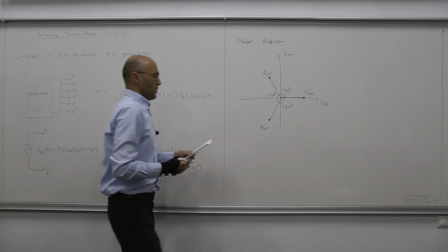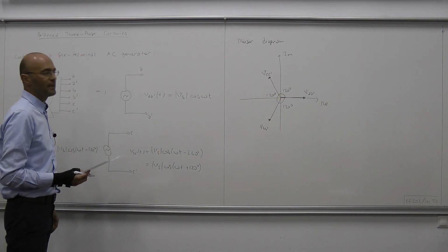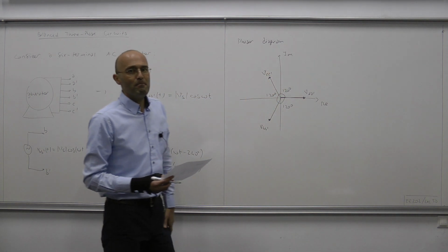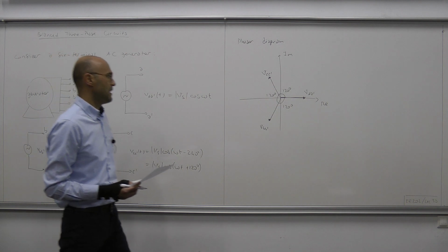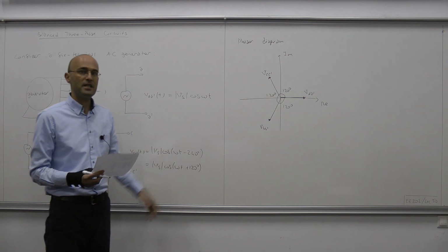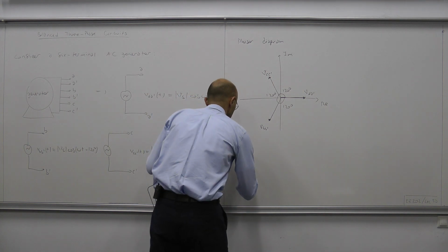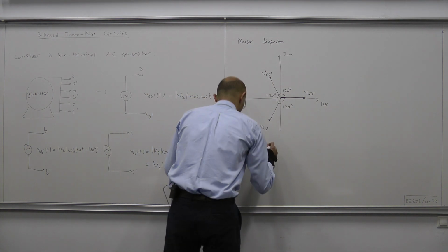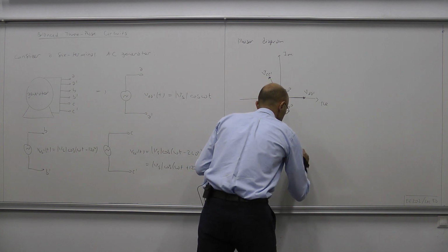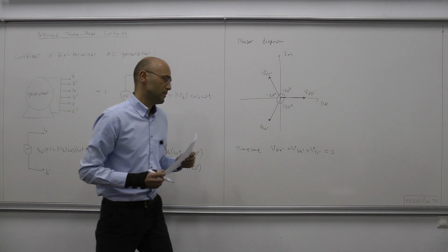Okay, so when represented through their phasors, the symmetry is clearly seen, and so that triple makes a balanced set. Namely, they have equal magnitudes, and the separation is 120 degrees between each. Therefore, their sum clearly will produce 0. Therefore, V_AA' plus V_BB' plus V_CC' produces 0.